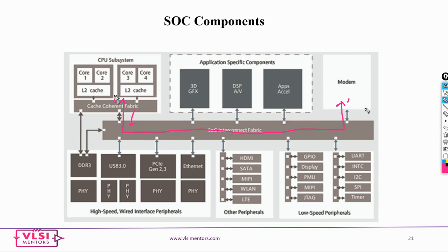If these two are done, and now you are taking something from USB to CPU, the way the chips are designed, each has to wait for its slot to communicate. The whole interface is designed using this interconnect fabric. It's a kind of bigger bus, so you are able to control each IP.